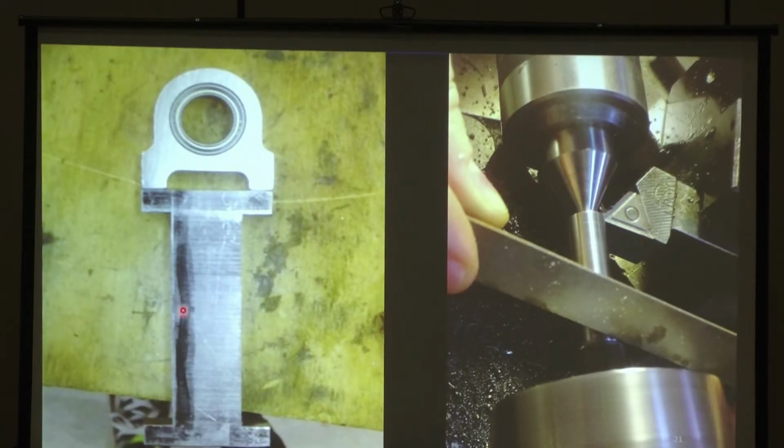These are our standoffs. There are actually 4 of them, and so there are 2 holding up the flywheel and 2 holding up the motor cradle. And then this over here is Sam starting an axle to match the taper on the flywheel. She used a micrometer to measure the taper and the diameter.